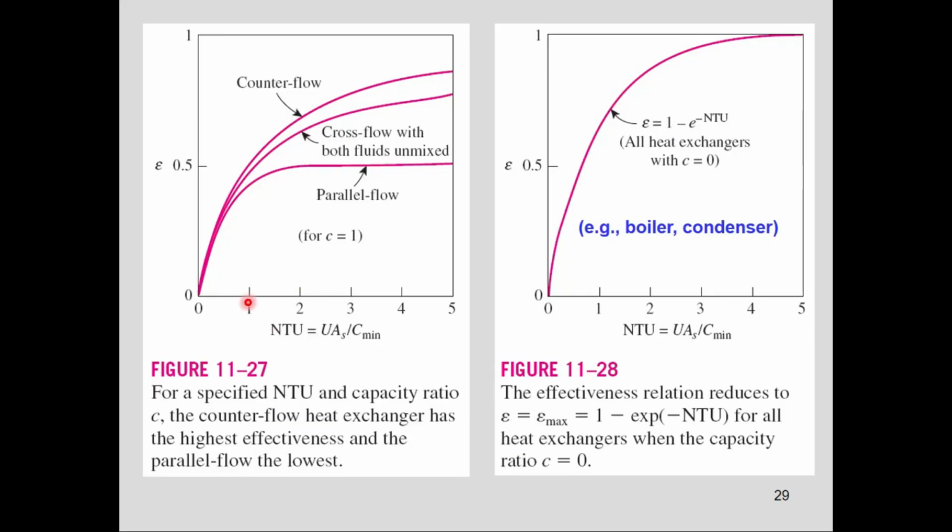So when the value of the NTU is less than 0.3, we cannot distinguish between the different capacity ratios, right? Here in the third point it is saying that when the NTU value is less than 0.3, the capacity ratio effect is independent, so we cannot distinguish between the different lines of the capacity ratio. It all becomes one line.